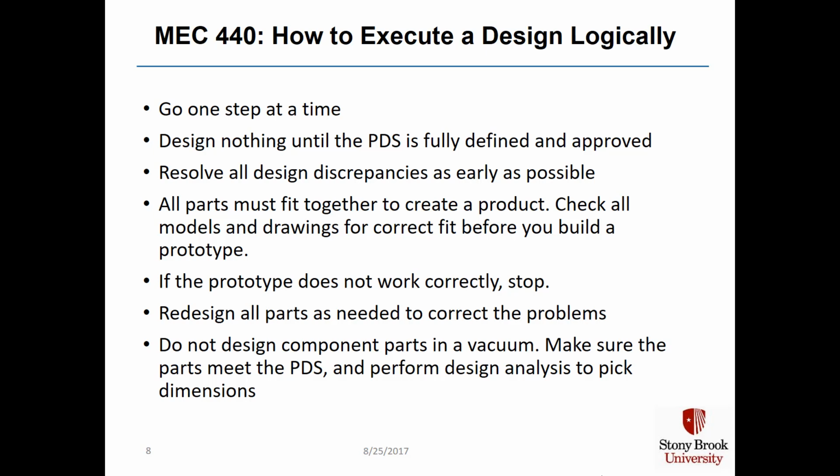Check dimensions carefully and make sure that all parts will fit together properly before you assemble them. If the prototype does not work correctly, stop and correct the part designs as needed. Lastly, make sure the dimensions you pick for components are based on analysis, whether thermal, stress, vibration, fluid, or machine design. You've taken all these classes. Now use what you learned.